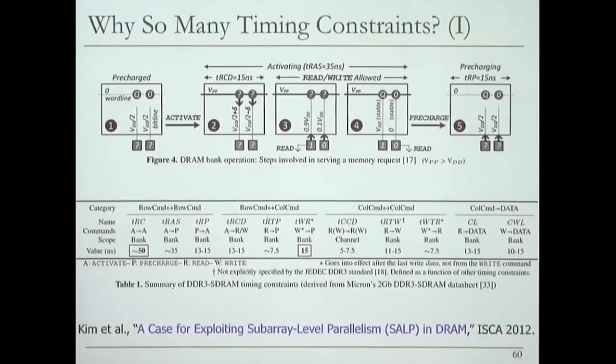You go over here, find it. That's precharge to activate, and it's at the bank level again, and it takes about 13 to 15 nanoseconds in this technology. So these are there for a reason, because the physical phenomenon takes some time, and we're trying to make the best out of the latency. Let me go over a couple more of these.